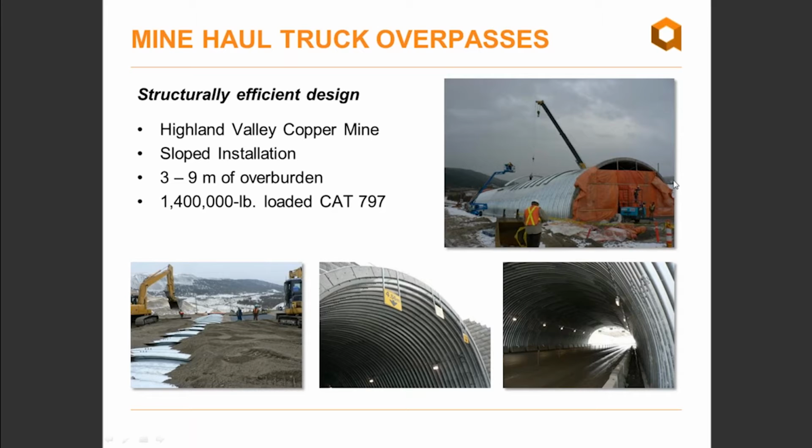You can see in the crown of the structure, obviously we're experiencing fairly high bending moments in terms of design. So sometimes in those cases we'll have some sort of reinforcement, typically just some additional bridge plate ribbing to add a bit of stiffness to the crown of the structure.